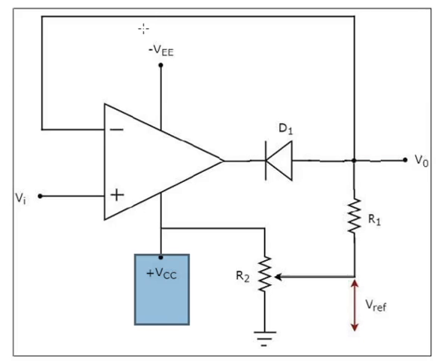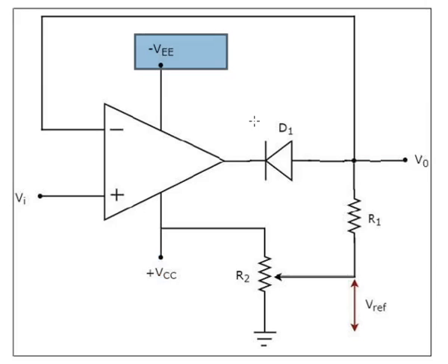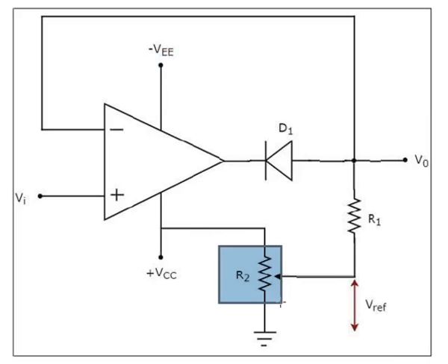Here we have applied plus supply voltage VCC and minus VCC. And we have used two resistances, one is R1 and another one is R2, and we have grounded R2 to ground. So this is the basic circuit of positive clipping.